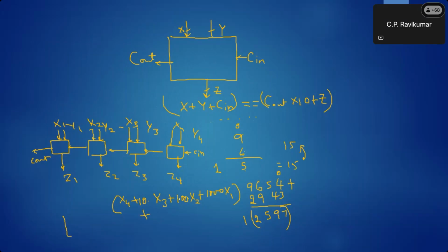So we write certain properties and then verify that these properties hold in all the test cases. Property checking is still unfortunately happening on a case by case basis. If I try 25, 30, 40 cases, looking at waveforms or print statements will be impossible.